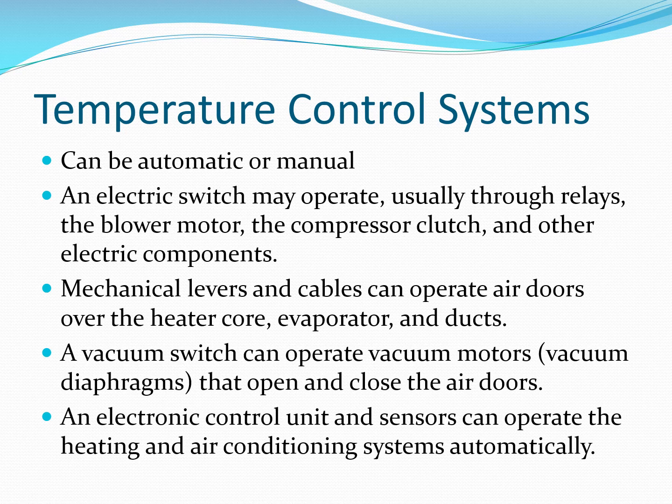I have seen what we call 4-zone systems. And what that means is you have 4 zones that are being controlled by this automatic temperature control system. So you'll have a driver's zone, a passenger side zone, and a mid-passenger zone for the middle passengers in an SUV. And then you'll have a rear zone for the rear passengers in an SUV. And each zone can be controlled separately. And they are controlling these through these blend doors and these mode doors. Most of these are fully automatic systems. So you can imagine the sensors involved.